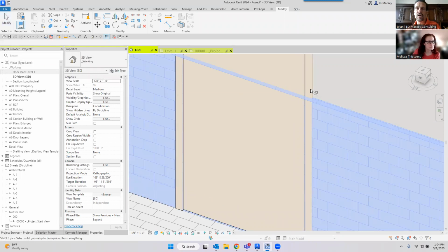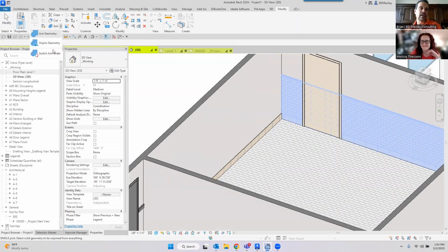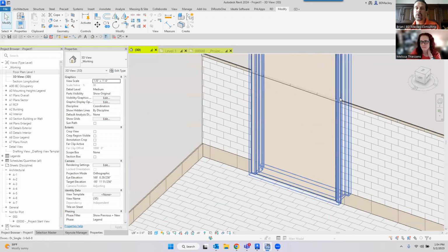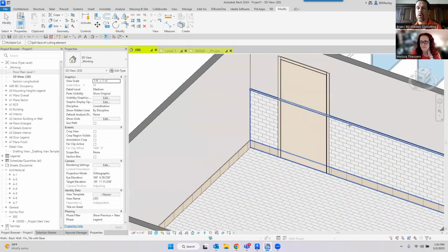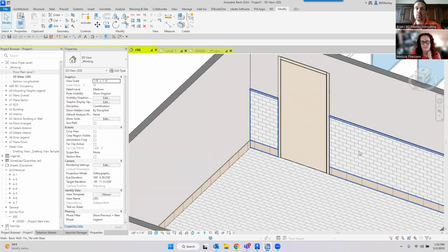And I'm like, oh, why have I not simply added, grab the wall, not the door, why have I not added the unjoined geometry? There we go. The option to put a void in the family. So now I can do just the cut tool as opposed to the join tool. Say, hey, cut this by the door rather than joining the two walls.